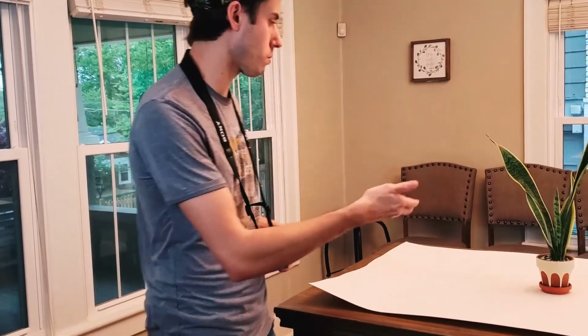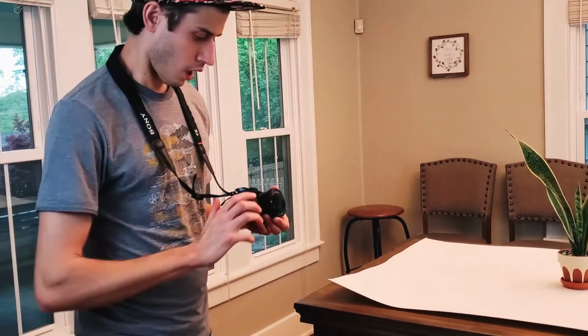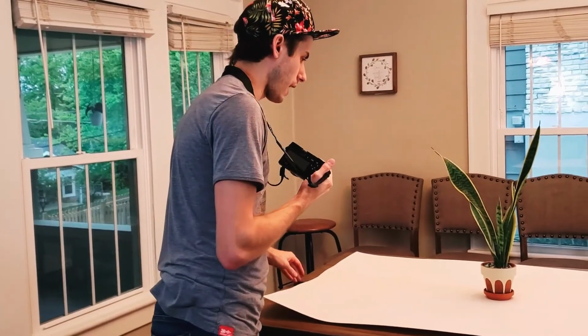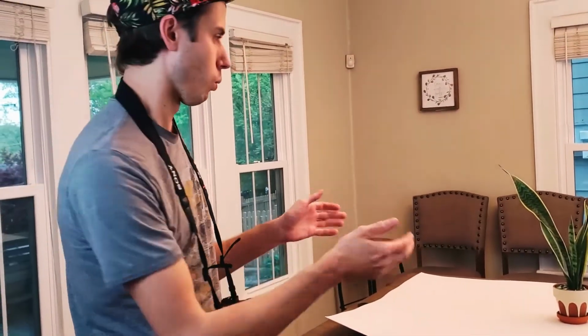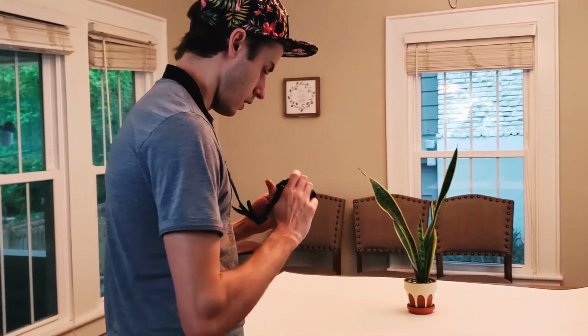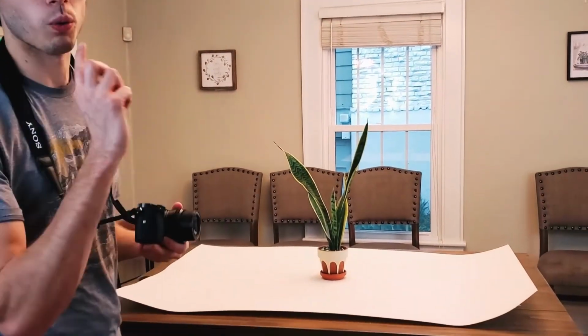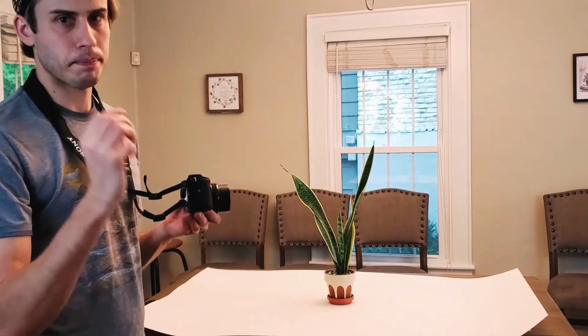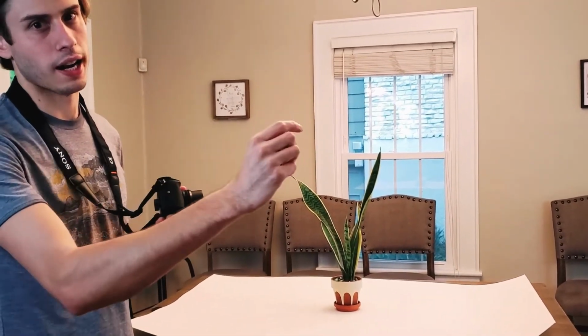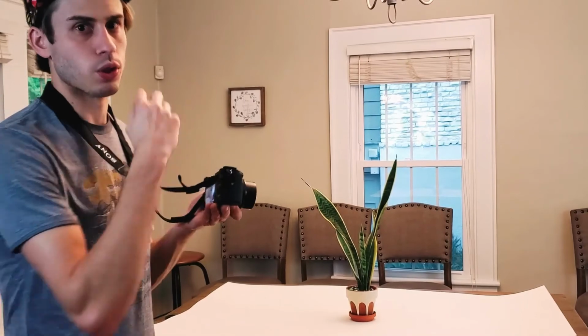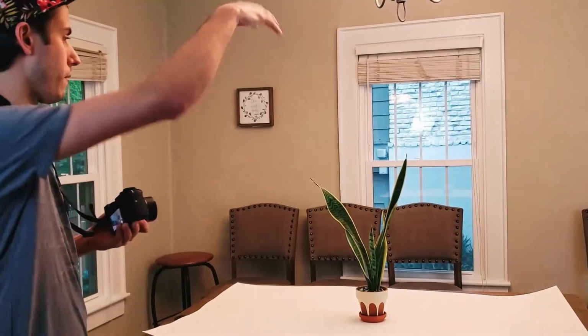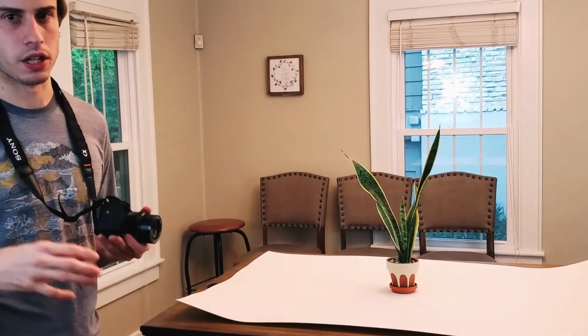So I'm going to kind of show you how I take my pictures. I usually will start from one side. I kind of pick sort of the front of my object, wherever I want to be, where I'm going to be coming back around, and somewhere that I can remember that I started. And we'll come in here, and usually I want to take a couple rings of photos. So you're going to want to go around the base of your object, taking pictures and moving about 5 inches each shot as you rotate around your object, taking pictures. And then you want to come from above, do the same thing from above. And usually I'll go from the very top and get some straight down photos so that I can make sure I'm not missing any information in my photographs.